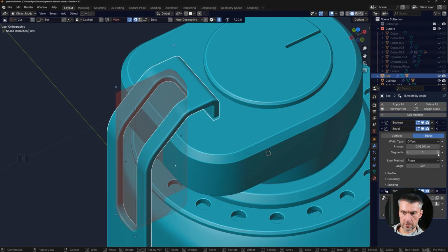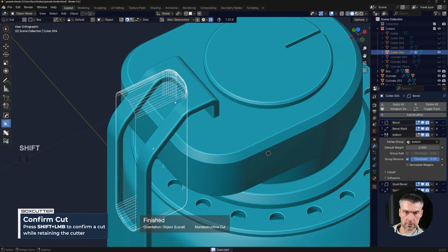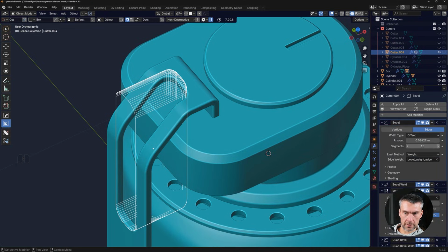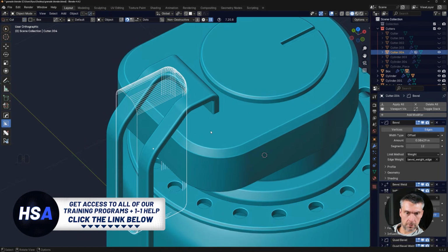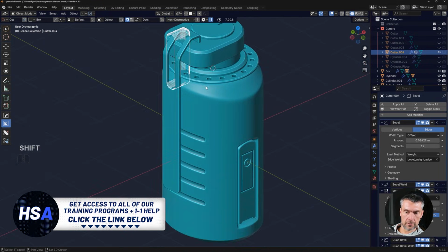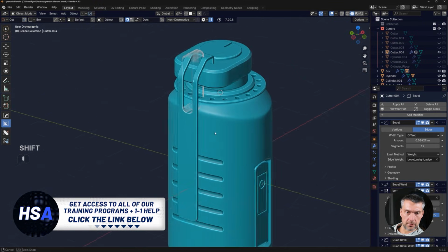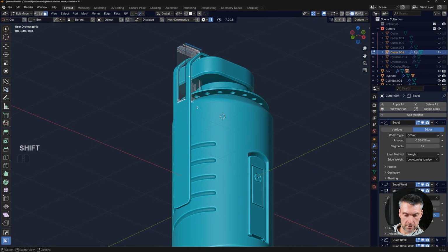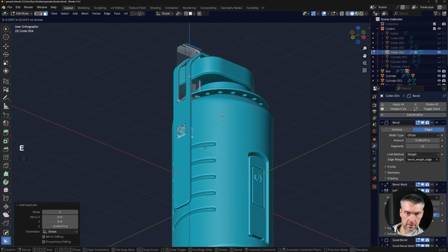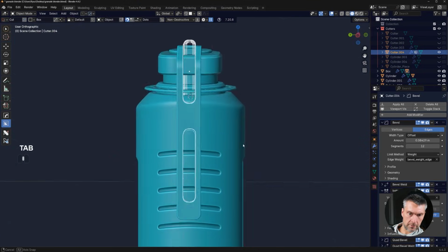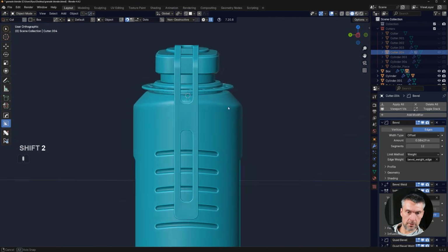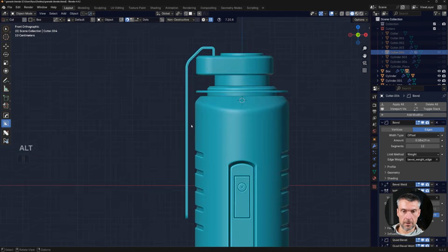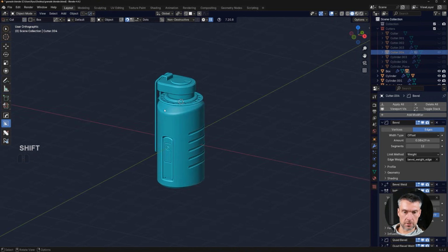And let's increase the number of segments. Shift click this to live. Grab this bevel and adjust it to, like, I would say 12, so it's really supple, okay? All right. Apply this. And then what we're gonna do, we're gonna grab this face here and shift the Z and drop it down and E extrude it. And you're gonna extrude it with a bevel. You see that? It's not one Boolean. Neat trick. I've aligned them perfectly, okay? So there you go. And I think we're peachy.